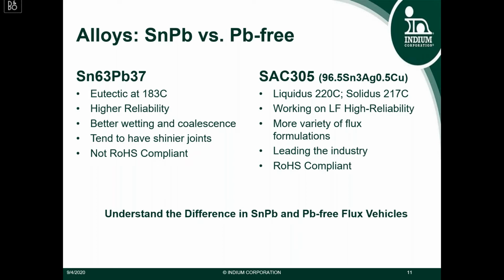Because tin lead solder has a lower melting point than SAC305, typically the tin lead flux vehicles cannot handle higher temperatures. They typically don't need to.